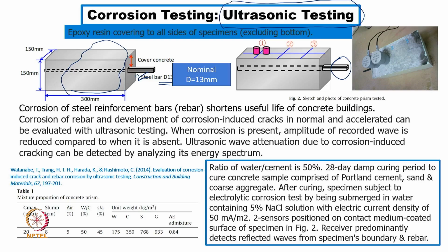And concrete will start developing a lot of tensile stress. We know the concrete is not very good in tension, it is very good in compression, but not in tensile loading. Then the cracks will form, and with more cracks, there are more and more chances of corrosion occurring. We know that cracks act as a kind of source of the corrosion itself. They give a path to the electrochemical solution. They allow a chemical cell or electrochemical cell to form, and then increase the corrosion rate. So, that is what has been shown over here.